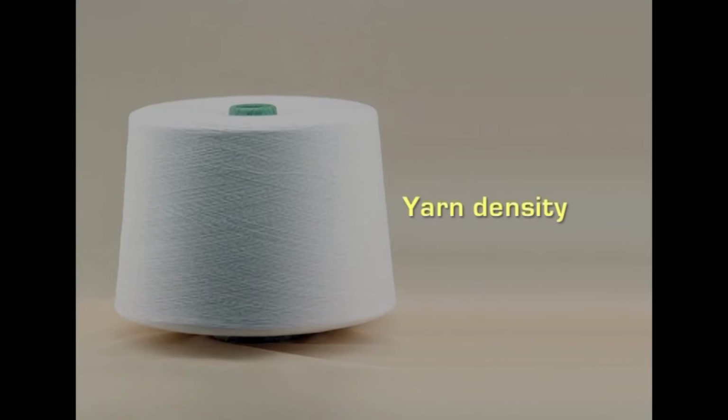Now, as I told you, yarn density has a lot of influence on the fabric properties. It influences the dimensional stability, the strength, the elasticity, the flexibility, the fabric cover, absorbency and air permeability also. Generally, staple yarns and textured yarns will have lower density than the continuous types of fibers. And as I discussed earlier about the different types of spinning methods, all these spinning methods would impact the compactness and the density.